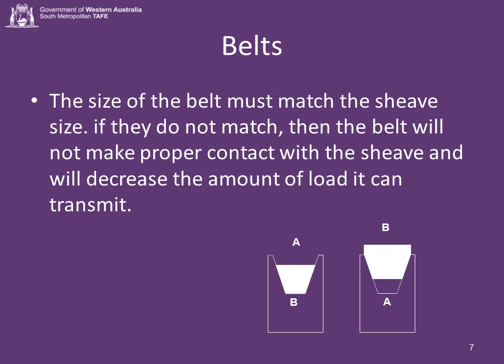The belts need to be matched with the sheave type, and they must be tight enough to prevent slippage. Examples of the different belt and sheave sizes are as follows. Fractional power V-belts, sizes 2L, 3L, 4L and 5L. Conventional V-belts A, B, AB, C, D and E. Conventional cogged V-belts AX, BX and CX. Narrow V-belts 3V, 5V and 8V. Narrow cogged V-belts 3VX, 5VX.